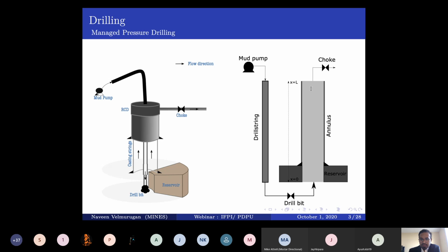And we again assume we have a constant area for the fluid flow, and at the other boundary of analysis, you have a choke, which is nothing but another restriction for your flow. It's a choke valve, right, which you can operate. And to couple this particular wellbore dynamics with the reservoir influx, if you want to model kick situations and for well control, then you need a reservoir model. And we only need the reservoir model for the open section. We don't need the whole depth, but just the section that is in communication with the wellbore. So that's what is shown here.